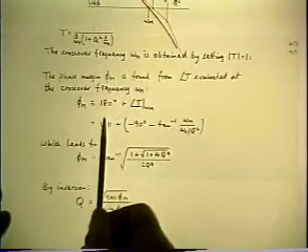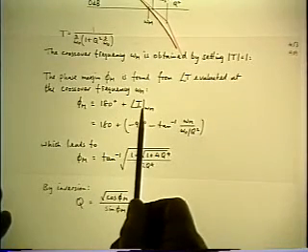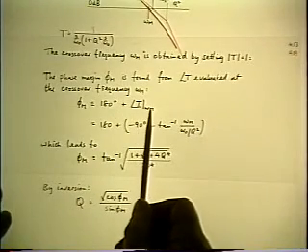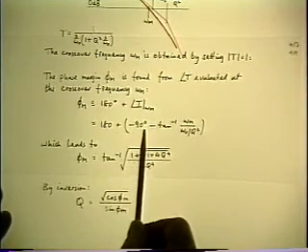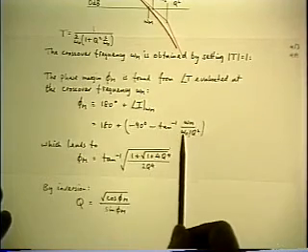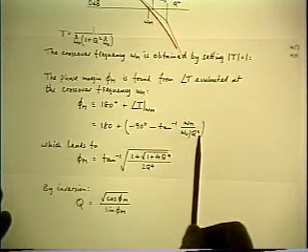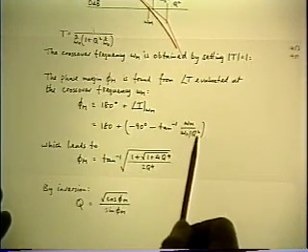you evaluate the phase margin, which is 180 plus the angle of T evaluated at the crossover frequency, which is minus 90 degrees from the first asymptote, and then minus arctangent of the crossover frequency divided by the second pole. It's how you find any phase angle from a single pole function. This is the omega 2.